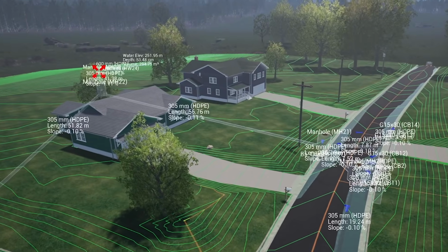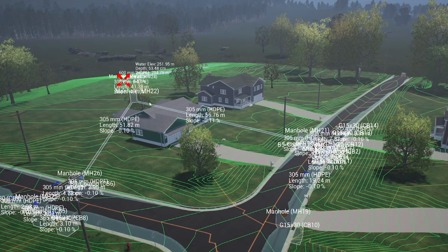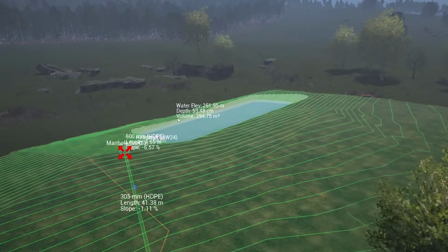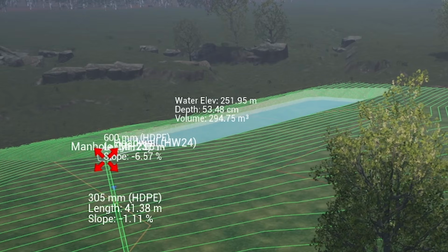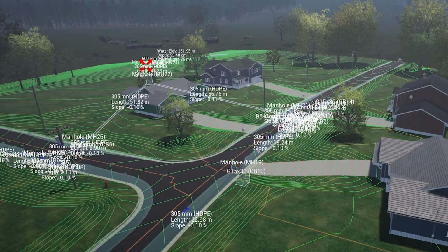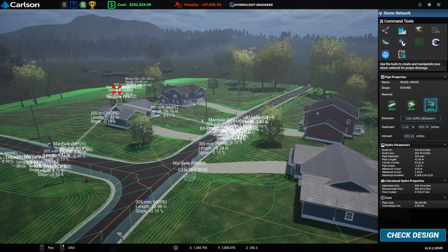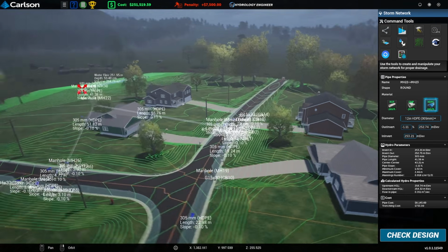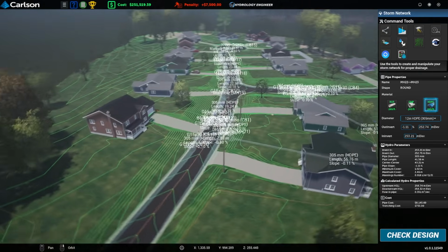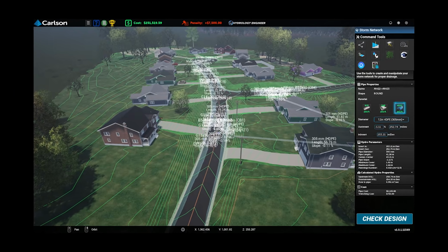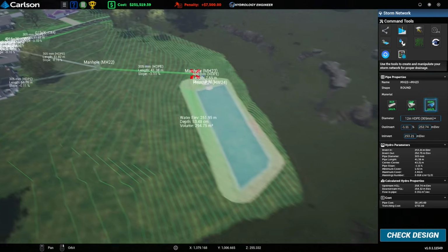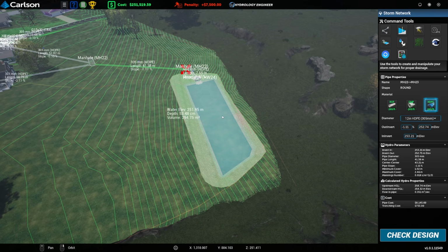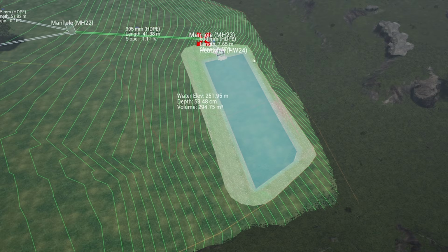Now you might think that's a bit backwards, because obviously if these pipes are only sized to take a 1 in 30 year storm, when a 1 in 100 year storm happens, that amount of water wouldn't actually make it to the pond, because your roads are going to flood because the water can't get through the pipes, because they're only sized for a 1 in 30 year storm. And obviously a storm that happens once in 100 years is going to be way worse, which yes is sort of correct, but it's more of a safety thing to make sure that this can never flood, because a pond flooding with such large volumes of water could be catastrophic.